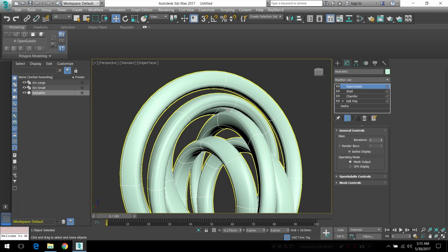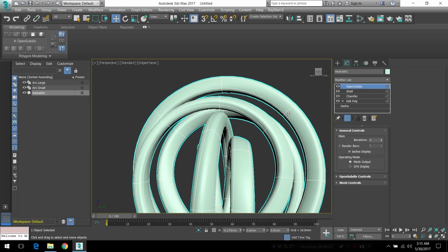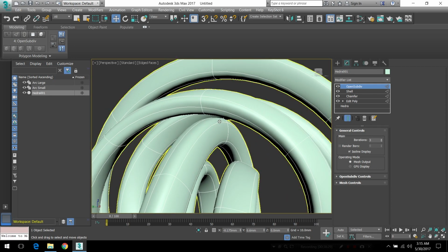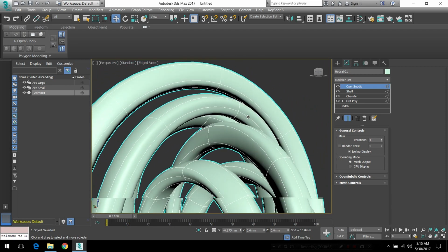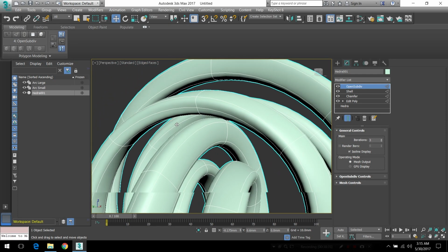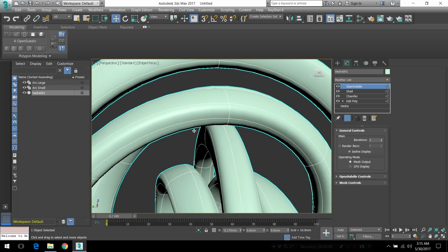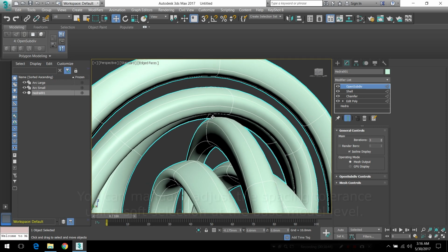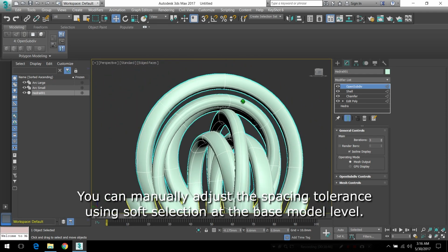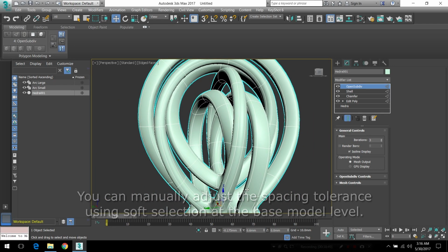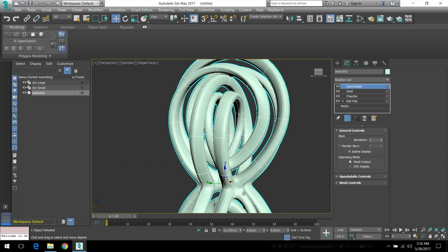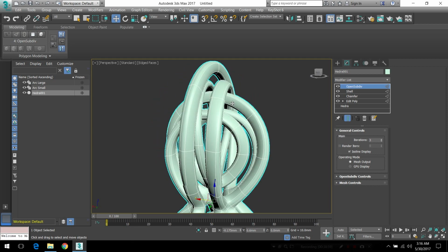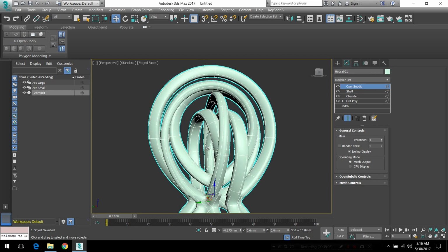All right, pretty cool looking object there, and you can see how the subdivision has provided a tolerance level here. These are no longer intersecting. So just beware on your 3D printer what your tolerance levels are, and this should be good for most 3D printers, especially if you're using a service like Shapeways with SLS printing. But in some cases, this may be problematic. You may have to fix that for certain printers. You'd have to measure that to see if the tolerance was enough so that it didn't cause any kind of welding to happen when you print.